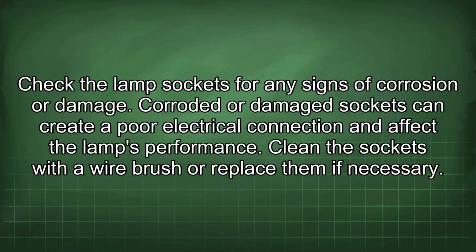Check the lamp sockets for any signs of corrosion or damage. Corroded or damaged sockets can create a poor electrical connection and affect the lamp's performance. Clean the sockets with a wire brush or replace them if necessary.